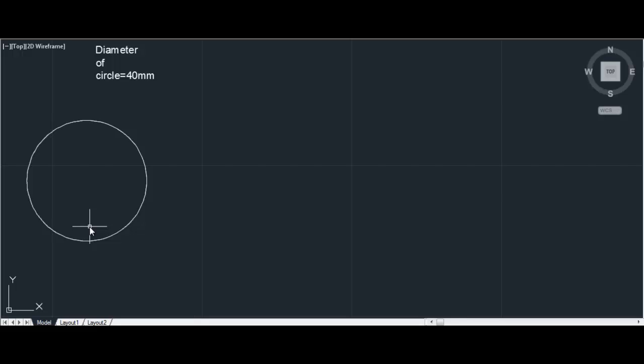So basically if we need to trace the locus of the point at the bottom of the circumference, we'll need to open up the circle. So imagine the circle as a bangle or a thread of the same length as the circumference. The length of the circumference here in this case is 2 pi r, that is 125.6. So I will be drawing a line of length 125.6.